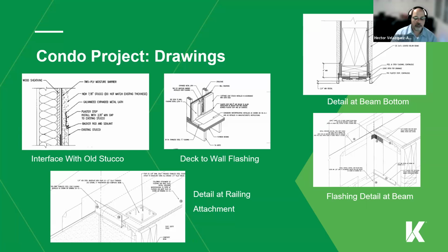People sometimes don't like seeing that. You can put a cover on it that lets water out, but please keep it open. There have been a lot of buildings that we have gone through that seal top and bottom. Now you trap the water. Now what? Now you're affecting the whole system. Let water come out. If you want to use something like a metal pan just to hide the hole because you don't want to see the hole, that's fine. But make sure that you don't seal it. Let the water come out.